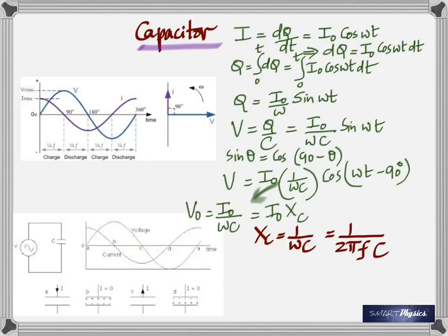So, whenever you do not want DC to flow in an electrical circuit, what do you do? Let's say there are so many branches and you do not want DC to go through a particular branch. Include a capacitor. The best practical thing that I can think of is this. In your speaker systems, would you like to hear a hum all the time? As the music is playing, would you like to hear a hum in the background? That is caused by DC. So you have a capacitor right before you take it to the speaker. What does the capacitor do? It blocks the DC and lets the AC go through.